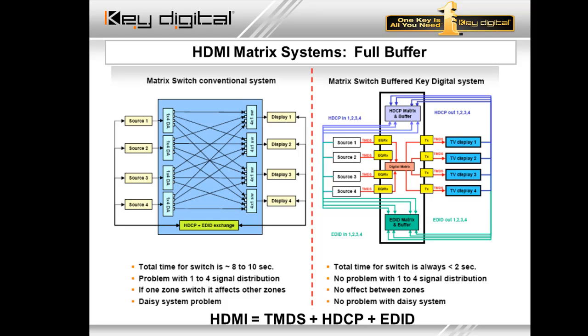To make a matrix switcher, you have 4 sources, you have 4 displays, for example. In the analog world, you were able to treat it just as a video and audio signal. Your video and audio from source 1 essentially is split 4 ways. Internally in that matrix, there's a 1x4 DA. Each output essentially selects from any of the 4 sources. There is a 4x1 switch. You combine those 2 things, you create a matrix, which is a pinnacle of a distribution amplifier and a switcher. That was all good and fine in the analog world. In the digital world, it created problems.